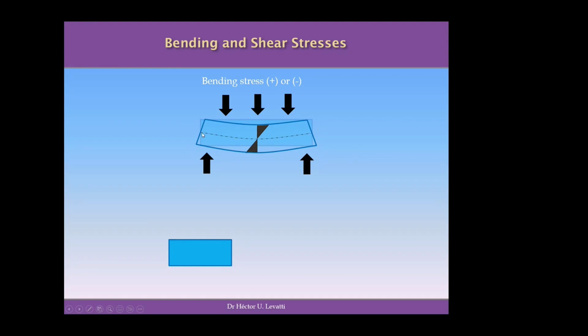But this is the reason why this axis is called the neutral axis, actually, because in bending, on the neutral axis, you always have 0 stress. So there is no stress on this neutral axis. So the stress is neutral in there. And the stress increases from this neutral axis to the maximum at the edges of the cross section on any beam subjected to external forces.